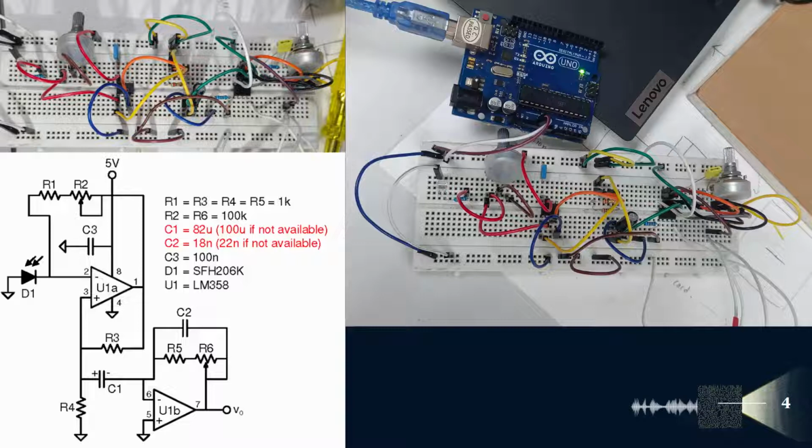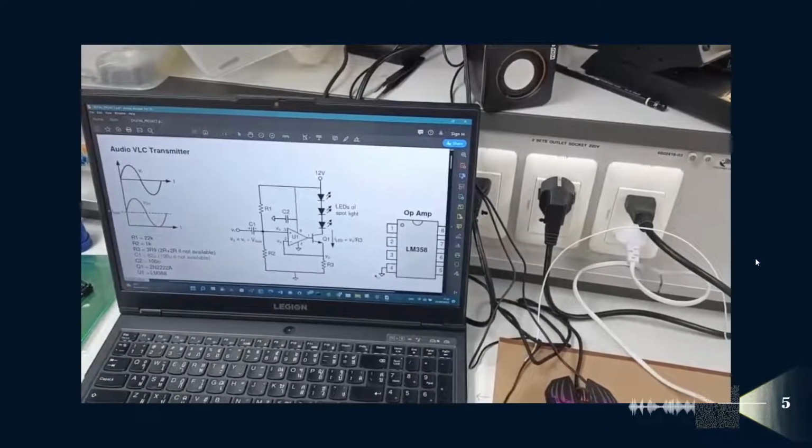Capacitor C3 is a so-called decoupling capacitor, which acts as an energy reservoir for the op-amp's power supply. It prevents rapid change of the voltage at the power supply pin of the integrated circuit, the IC. It needs to be placed as close as possible to power supply pin 8. A detailed explanation of the decoupling capacitor can be found in the datasheet of the product, which is also attached with the project report. And next we're going to see the video of how this project worked.